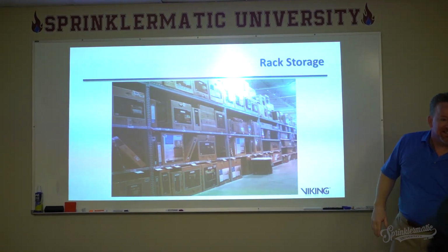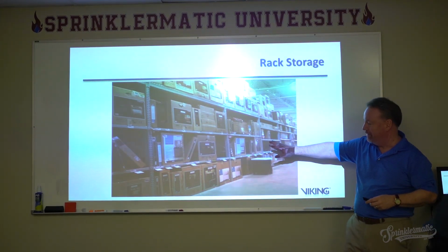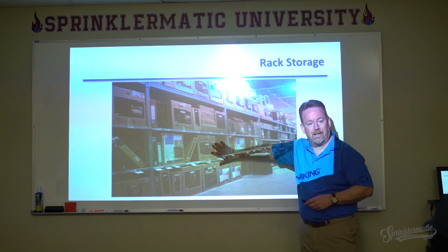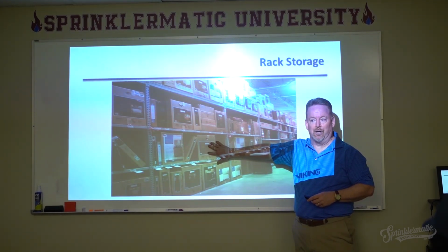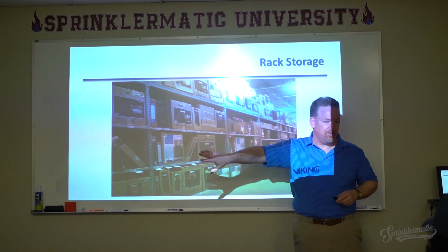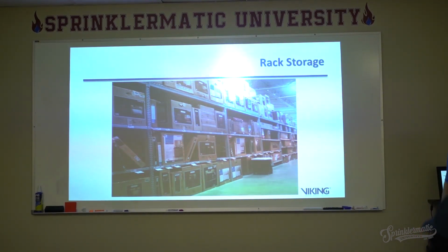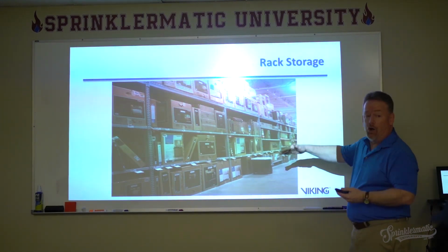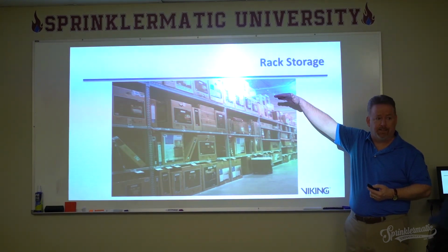This keeps everything right in place while the fire is going. It doesn't fall off, doesn't do anything else. It just burns. So rack storage becomes the biggest challenge. Protecting against rack storage is a bigger challenge even than pile storage. We can go much higher, 48 feet high in rack storage.